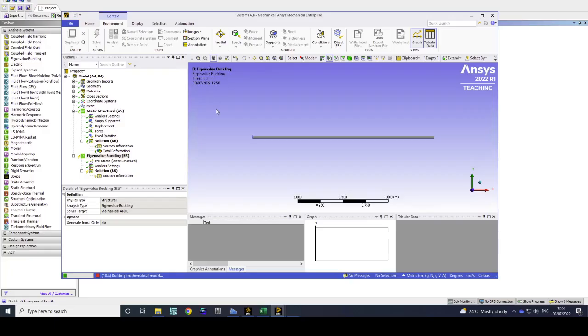So you remember, this is forming the eigenvalue problem and finding the solution that would make the net stiffness 0. Essentially, it will find the critical load and the associated buckling mode shape for that critical load.